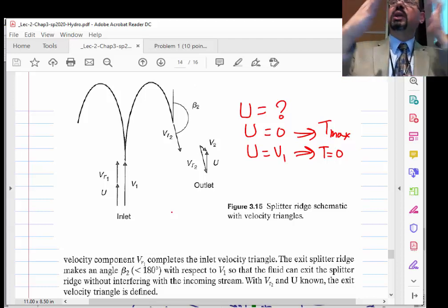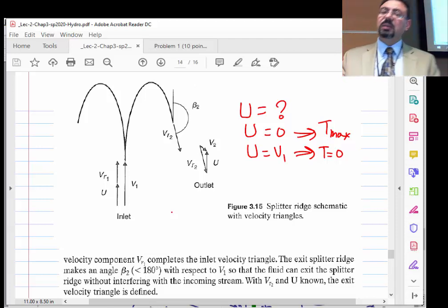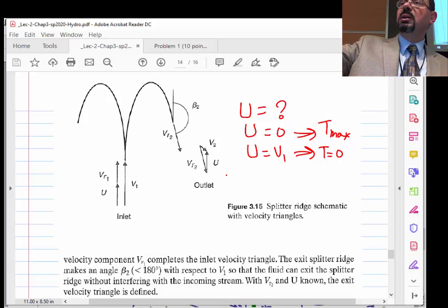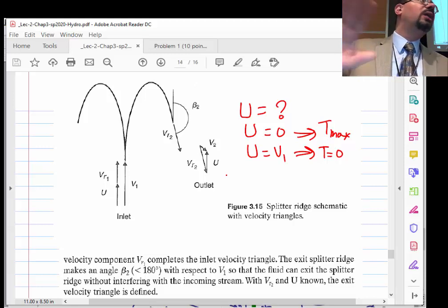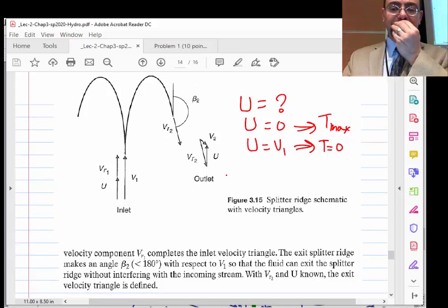So they try to get it as close as possible, because you still want to send the flow out away from the incoming flow. But the point is, a hydraulic turbine, theoretically speaking, can get 100% efficiency, because all that kinetic energy shooting from that hose can theoretically be slowed down to 0. Keep this in mind for the next lecture, when we think: what happens with the wind turbine? Can a wind turbine do the same and slow down the incoming velocity all the way to 0, so that we can get 100% efficiency like those guys?